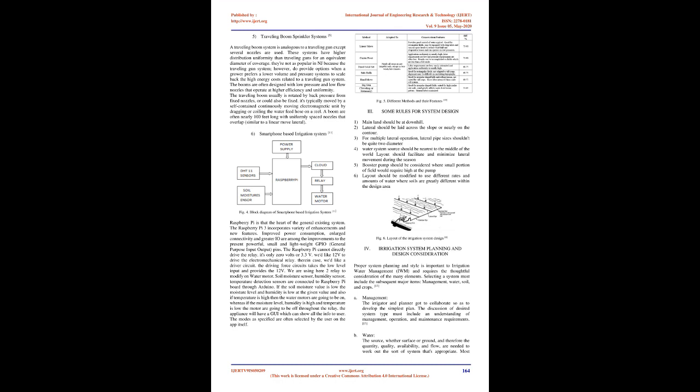When the corner unit starts, discharge flow in all other heads is reduced. Overall field distribution uniformity is affected by the corner arm. Typically, 85% of maintenance is spent maintaining the corner arm unit itself. Due to inadequate maintenance in corner systems operating all the time, total field application uniformity is reduced even further. Many techniques have been developed to reduce energy used, lower system flow capacities, and maximize water use efficiency.